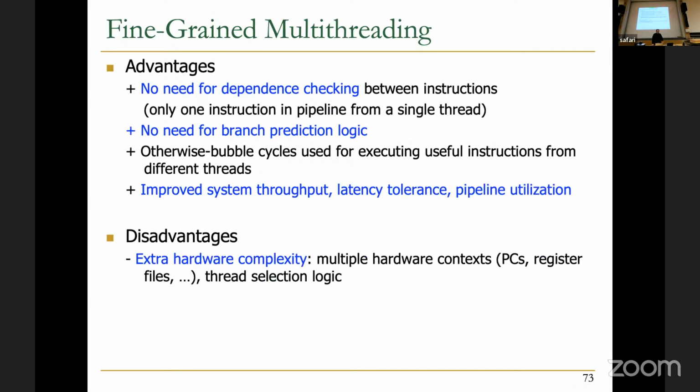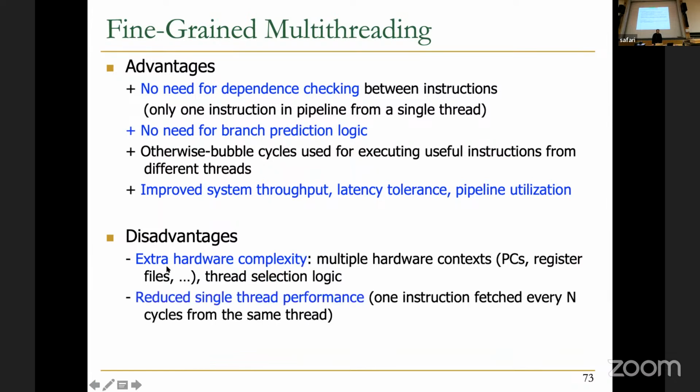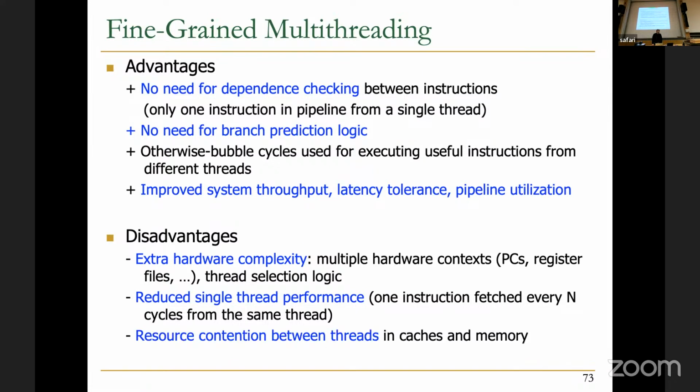However, it also has some disadvantages. One important one is extra hardware complexity, and you will reduce single thread performance, since there is one instruction fetch every n cycles from the same thread. And as I said, also resource contention between threads.